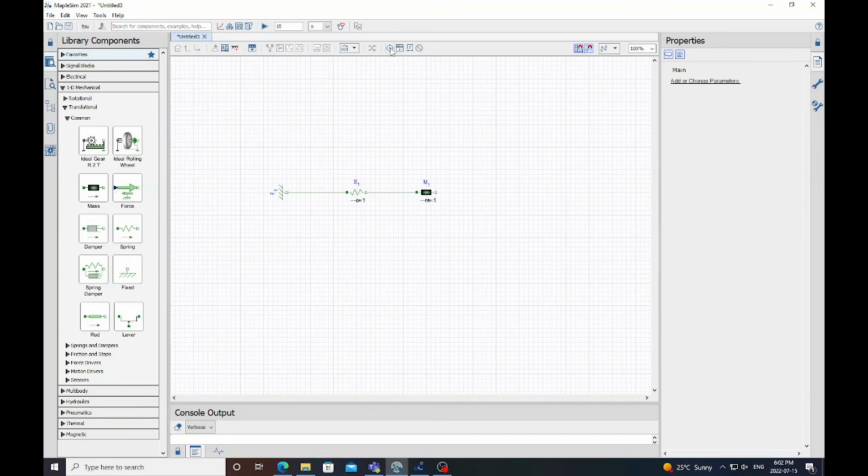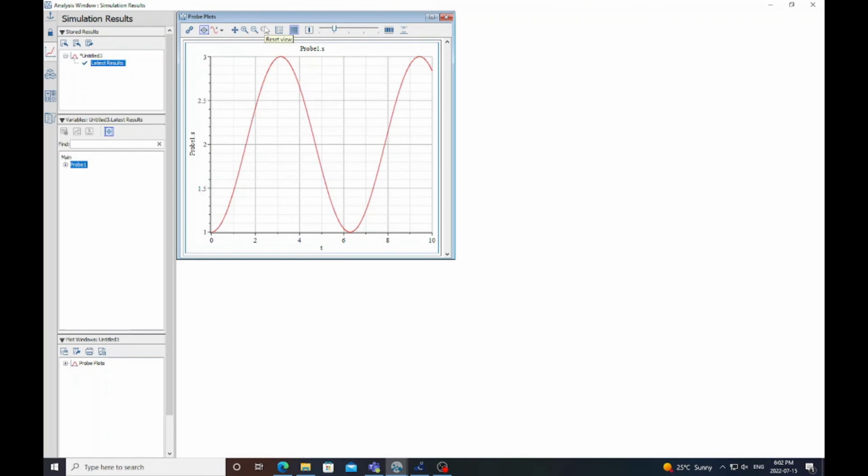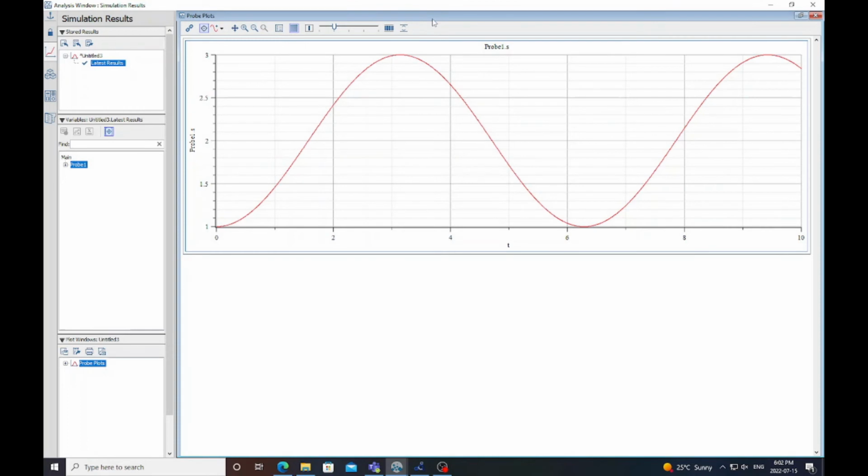We also need to specify what we want to measure, and we use a probe for that purpose. We can choose the different measurable quantities and then run the simulation. Running the simulation takes a few seconds. The user can explore these plots by selecting the type of cursor, the number of plots they wish to see in a row, and explore the results using Excel or a CSV format export. Now that we have our simulation results, I'm going to save the result in MapleSim for future reference.